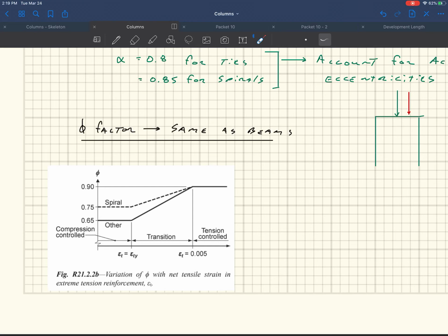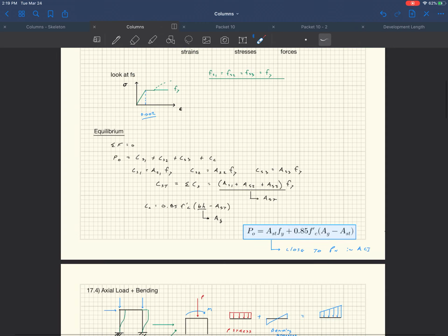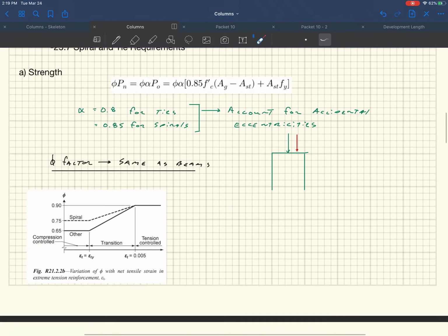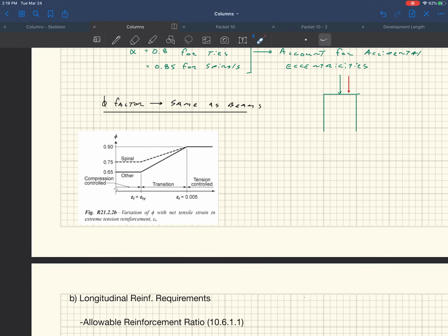With concentrically loaded short columns, these are tensile strains. These things are loaded up in compression, only compression. If you look back at our capacity derivation above, we assumed that they're all in a compression of 0.003 for a concentrically loaded short column. They're all at 0.003. Since they're at 0.003 in compression, they actually aren't even on this graph. They're over here, over to the left here is where columns end up being. I'll make that red so it stands out.